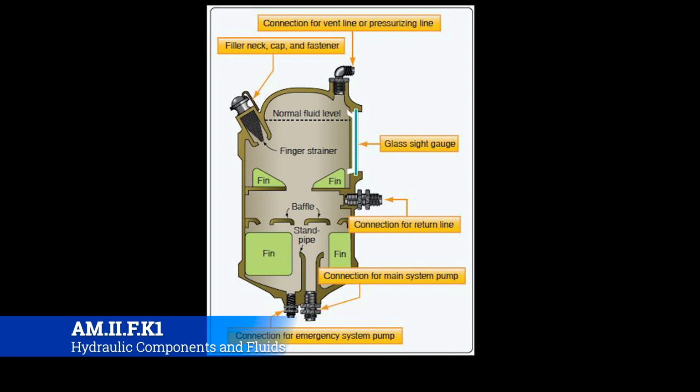And so you always wanted to make sure that the helicopter was cold, and then the transmission fluid was at the correct mark, because then you know that is the right amount that is designed for that system. You never wanted to service it hot, because you could over service it as well, which isn't what you wanted to do. So that's something to keep in mind.